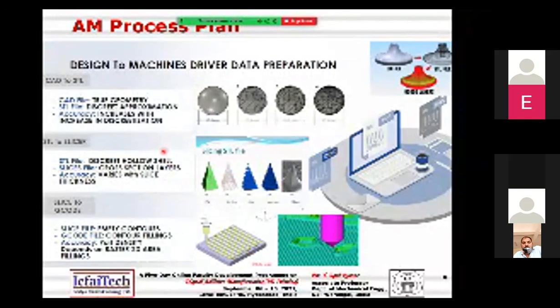For slicing, once you slice it, you are going to generate the contours. First you are going to generate the contours, and those are empty contours, which we need to fill up. Typically you may use G code for filling up these contours. Again, you have a lot of freedom here. How do you fill it up? You can have a different filling density, or you can have a different path strategy.